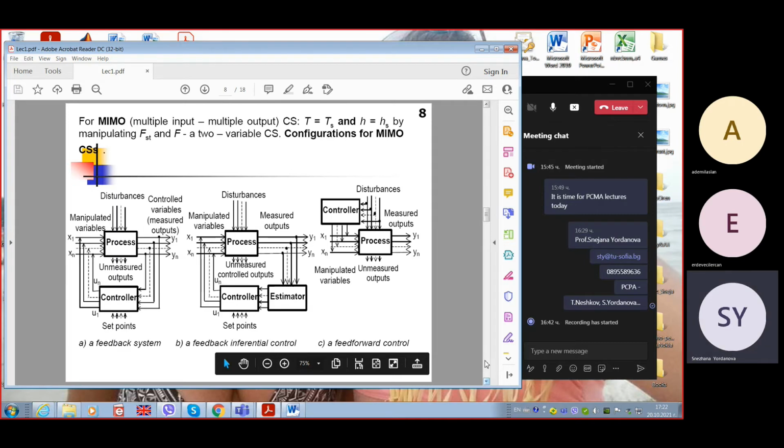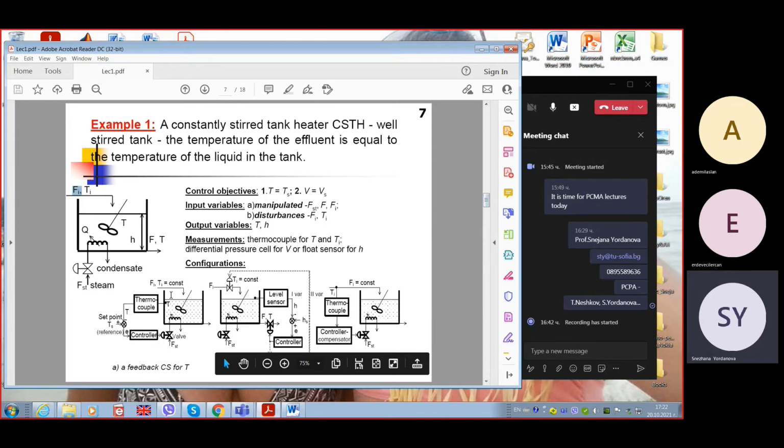We can separately control temperature using a closed loop. This means our control action on the valve is aiming to change the temperature, the output of our plant. So the plant is relating the output information variable with the input manipulated variable, or the controller output.